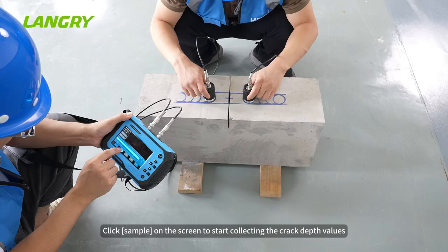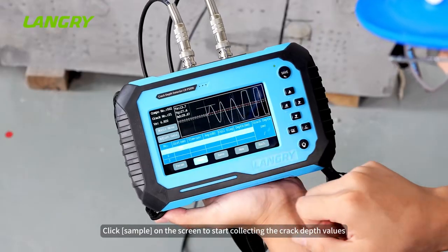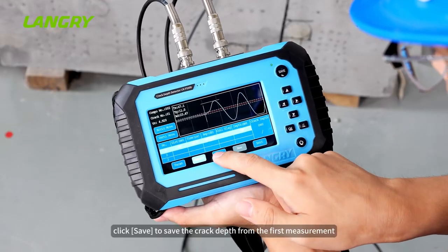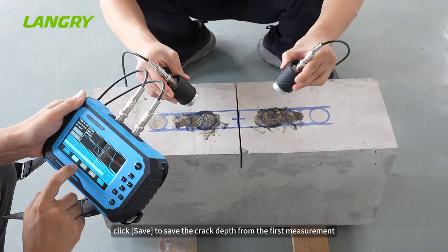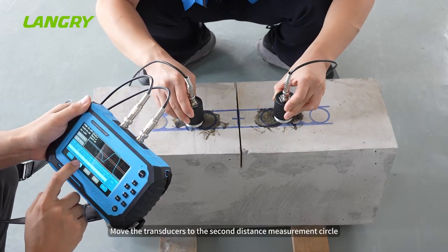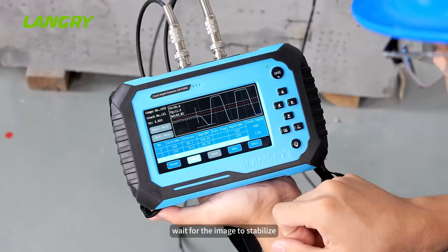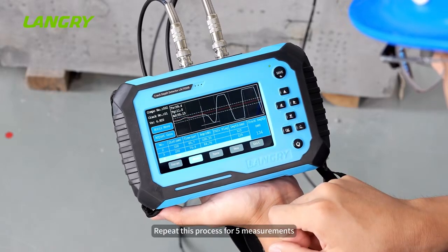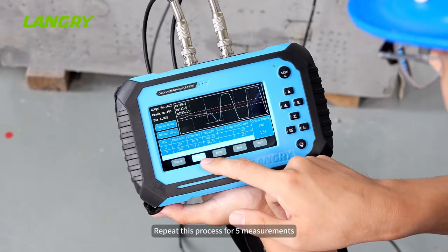Click Sample on the screen to start collecting the crack depth values. After the image stabilizes, click Save to save the crack depth from the first measurement. Move the transducers to the second distance measurement circle, wait for the image to stabilize, and save the second measurement value. Repeat this process for 5 measurements.